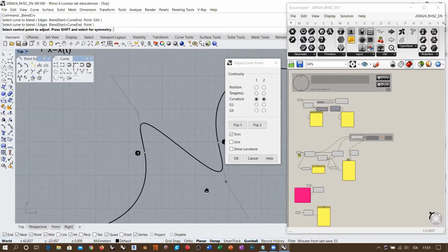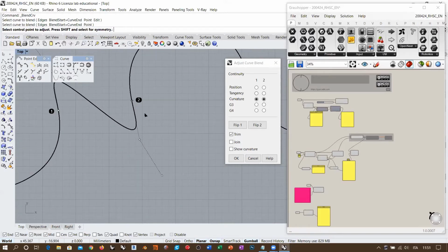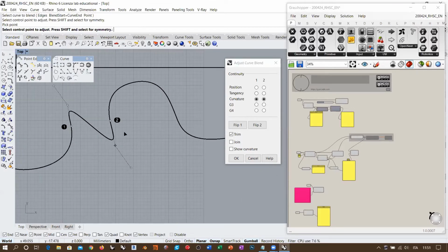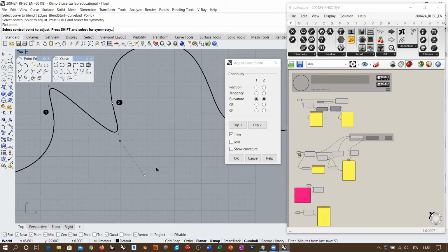And moreover, take a look at what happens, for example, if I tweak the position of these control points. If I move this, the third control point moves accordingly because it must maintain a symmetrical set because it needs to create an arc. But this is no surprise, right? If I move the center control points, the third one is simply symmetrical with respect to the center of a virtual curvature circle, which we will be discussing later. So you can see what's the relation between these 3 points if I move the second one. But what if I move the third one? And you see that the second one can only move along the tangent line, of course, right? So there is a strict relation between these 3 points.